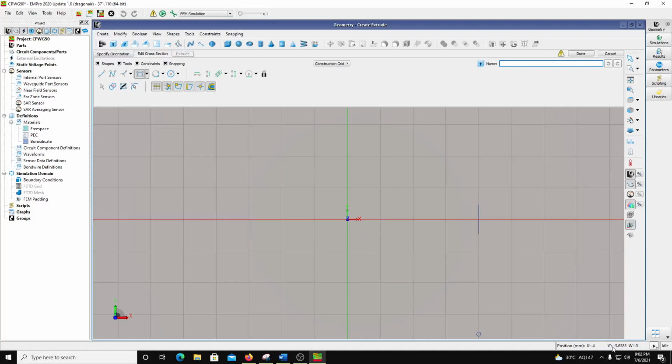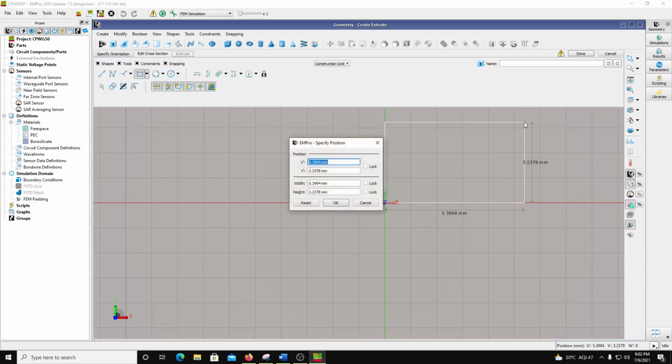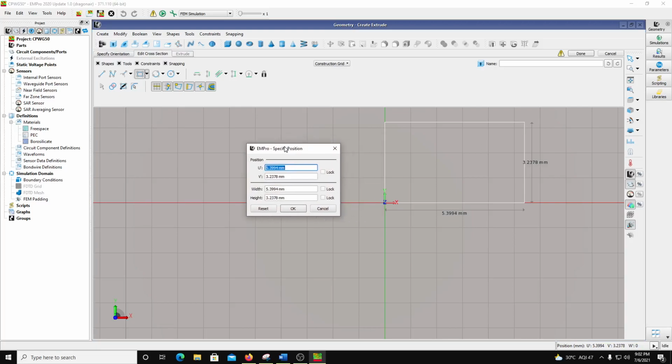So you can see where your mouse is. It will show here 0 0 if I go to the center. So that's 0 0. Then I can basically, this is a 2-point method to draw a rectangle, right? So first vertex and then the diagonal vertex. For the diagonal, I can always put a tab. So if you put a tab, then this appears.